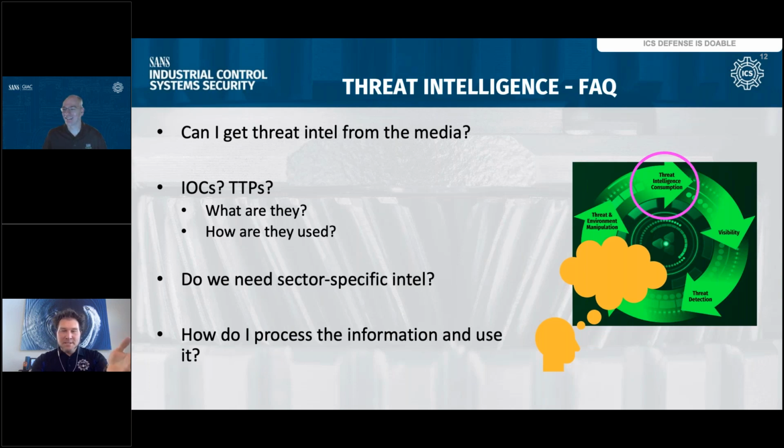It's great how you mentioned TTPs, or like, you can get ahead of it. It's the advanced kind of thing you can do. It's proactive security, whereas IOCs is really that scoping, could be a one-time thing. Now, from a practical perspective, and Steve kind of mentioned this, the critical assets that you're going to want to scope on your endpoints and in the network are really around those top 4 or 5 assets in the ICS. So network communications to and from your HMI, your PLC rack as an example, your historian, and the engineering workstation. Starting there is a huge return on investment, because you're directly and initially protecting your critical assets in ICS. So great place to start.